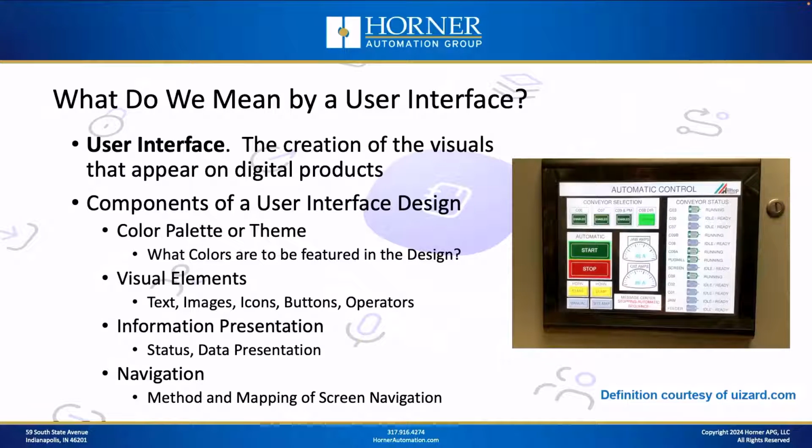Those sorts of things. How are we going to present any data or information? What does the text look like maybe for any instructions? If there's a status of the machine we need to get across to the operator, what's the best way of doing that? Graphically or with some sort of lighted push button simulation? All those sorts of things. And then of course, navigation. What screens do we need to develop and how are users going to get from screen to screen efficiently and in a very obvious fashion? Those are all elements of user interface, of course.